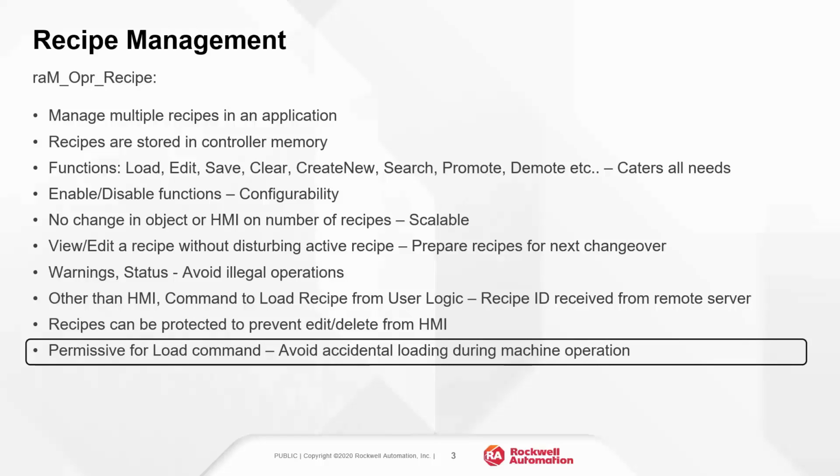The object has a load permissive input to permit the recipe load from HMI. This input can be linked to machine stop status, so the operator can only load a recipe when the machine is in stop state.